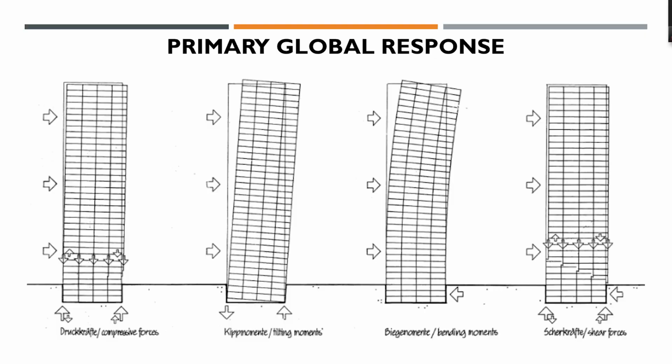So this is also from the same book. It best tells you, in very simple layman terms, how a tall building system works, right? And being civil engineers, you already know, but I just want to make sure you understand that when you have the lateral load, you get the lever arm with upward and downward reactions here, and then vertical reactions are created, and you get a drift.